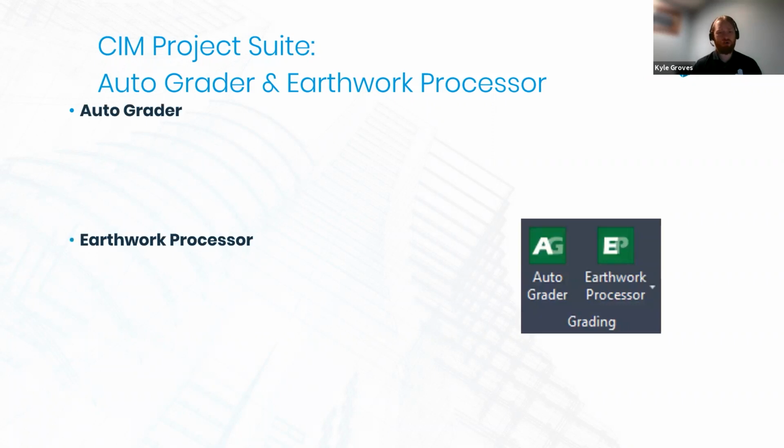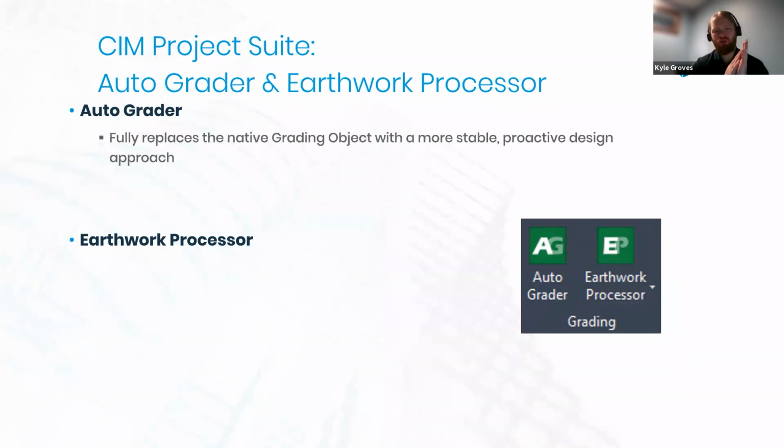So AutoGrader, Earthwork Processor, you're going to go to the CTC website, you're going to download the tools, you're going to install them. You'll see a big ribbon inside Civil 3D. I'll show you that in the software, but we're looking at the grading panel of these, where we'll see AutoGrader and Earthwork Processor. So AutoGrader's job, at least when it comes to area site-based grading, is it was intended to fully replace the native grading object.